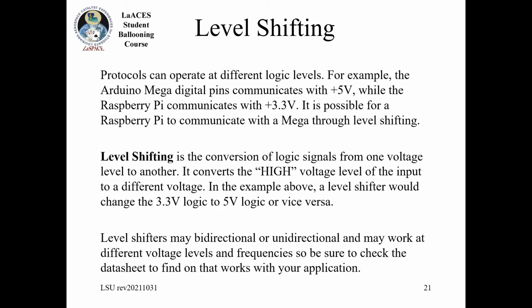But like I said, the level shifter basically converts, on the input side, you'll have a high, and it'll convert it to the appropriate voltage to be a high on the output side. And these are usually designed to work with specific voltage ranges and specific speeds or frequencies, data rates. So if you're using one of these, you want to check out the data sheet and make sure that it's the right version for what you want to do. So that's it for the lecture.